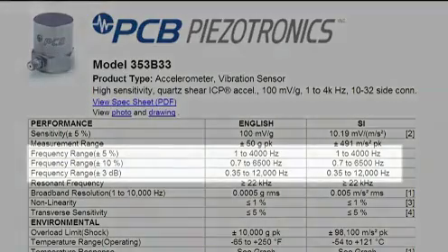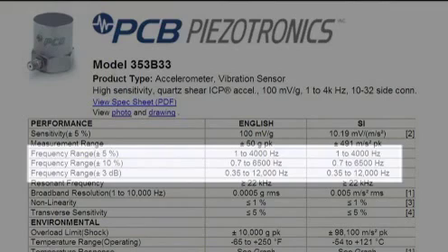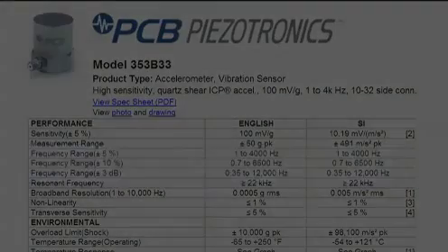The frequency response of an ideal vibration sensor is a flat, straight line. The frequency response of an actual vibration sensor, however, deviates from this. The measured amplitude frequency response of a sensor is typically scaled in percent from the reference sensitivity.